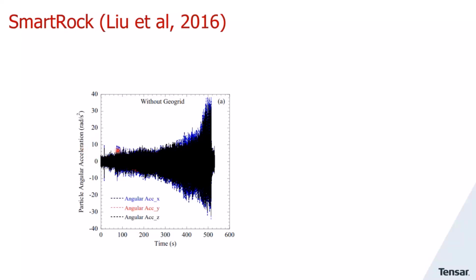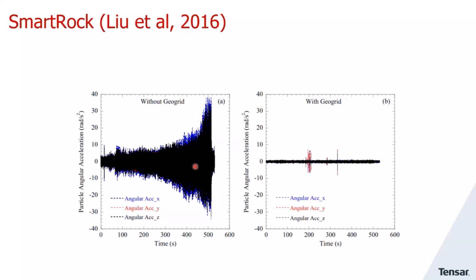And as we can see, the more passes we have, the easier it is for the stone to move and to rotate, which in turn causes a loosening up of the granular material, abrasion, and loss of stiffness. If you then compare the test results with